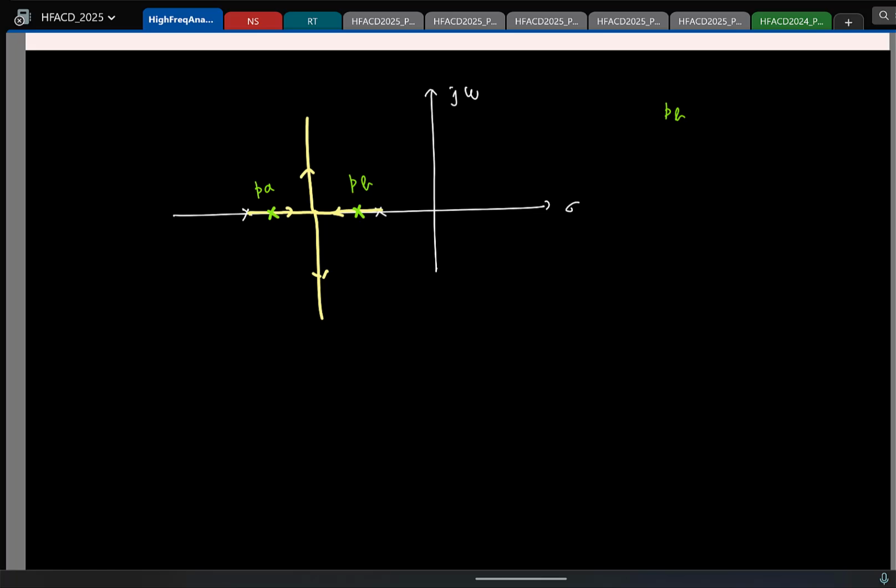It decides the settling, right? So right now this is the slowest pole, or the smallest pole. This is the slowest settling. So I want the system to settle fast. So what do you want? How do you want this dominant pole to be? Do you want it to be at a higher frequency or lower frequency? Let us say you keep increasing this, but if you keep increasing this, what happens to PA? That tries to come this way. So then what is the optimal point to keep?